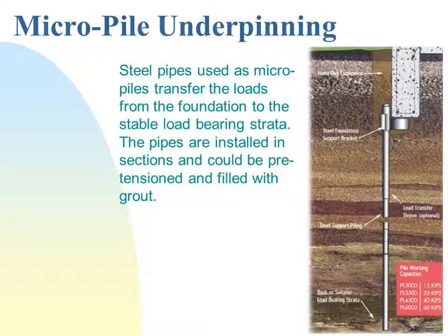This micropile is a steel casing, a steel pipe, which has some pre-tensioned cables in it. So you pre-tension the cable and then you grout. Now it has a very high capacity. However, the cross section is not that big, so that will make its construction a little bit easier. However, its cost will be much higher for sure.